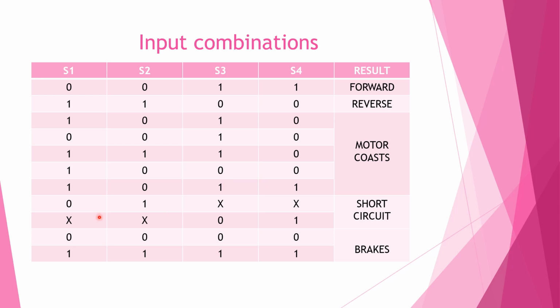And at this condition, you can see these two transistors S1 and S2 alone are on, that is, a PNP and an NPN on the left side of the H bridge. This alone will be on. So for that, a short circuit happens, and the VCC will be pulled down to ground. That will cause a short circuit for the battery on the power supply.